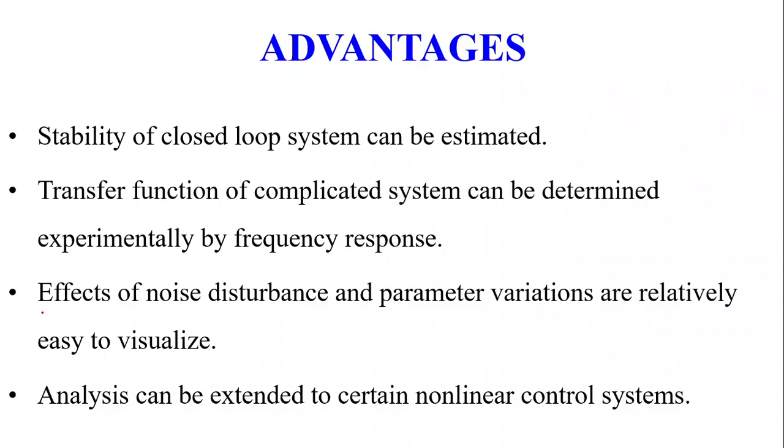Next, we are going to see the advantages of frequency analysis, and where we use it. The first purpose is that the stability of the control system can be estimated using frequency response, and the transfer function of a complicated system can be determined experimentally by using frequency response.